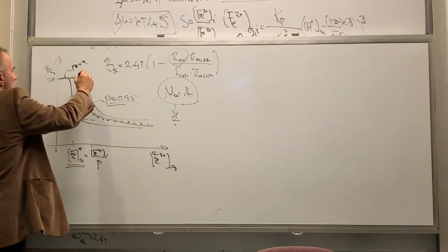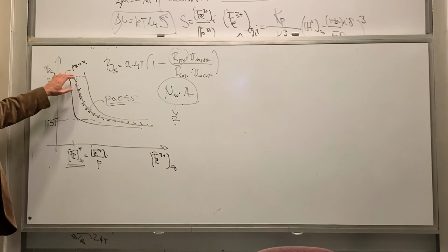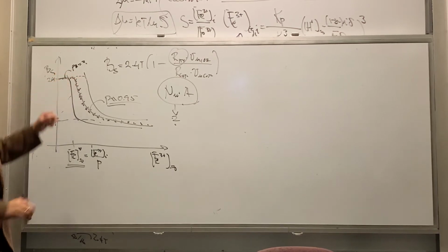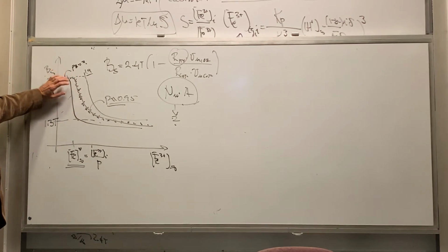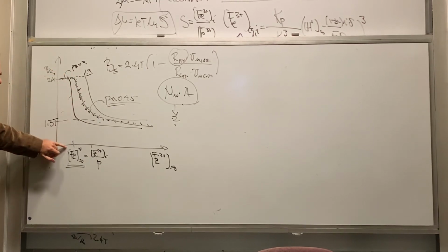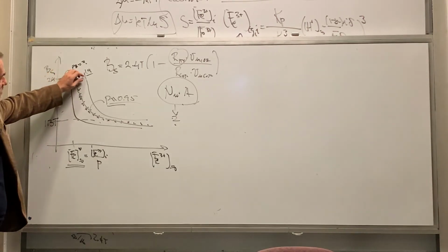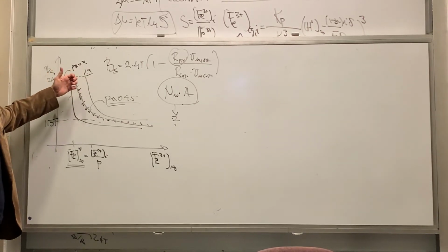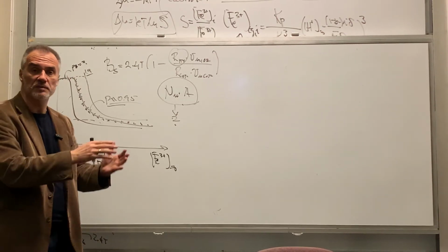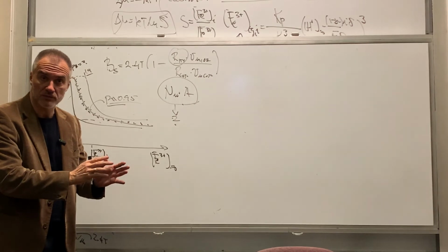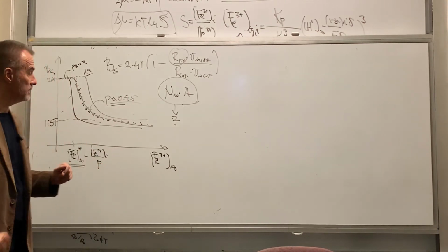So now I can see if I'm reading, if my pH reading is 2, but it's actually 1.9, actually I'm in a safe place, because if I think my iron 3 concentration is here, actually my region of stability is extended, because the lower pH gives me an extra ability to run the process, because the depletion of hydrogen plus ions at the interface is not so severe, so OH minus is not so high, right?